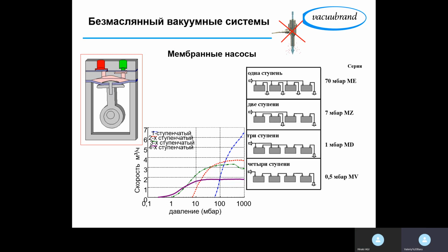Even if you have a pump, let's imagine you have a system with a leak rate of 0.1 cubic meter. In case of a leak rate of 0.1 cubic meter, there should be a relatively high hole in the system. So you have a pump with the same performance as the leak rate. Although you are pumping something out of the system, the same amount of air at the same time goes inside the system. So the system will never have any vacuum in it at all.